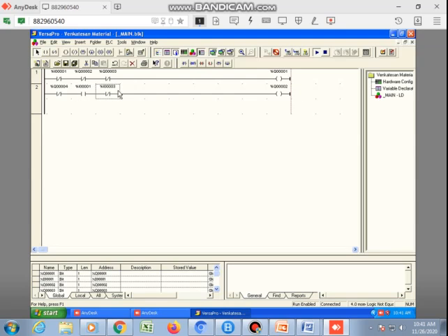So this should stop, in the sense this entire condition is together. This condition is a separate one. So these two conditions should be looped. I should use sealing between these two to maintain our output, because since we are using a limit switch, when I1 goes high, I will start running forward. When I pick the material, this will stop. So by that time it will not run. So that should be disabled. I will show in the demonstration with respect to hardware how it is helpful.